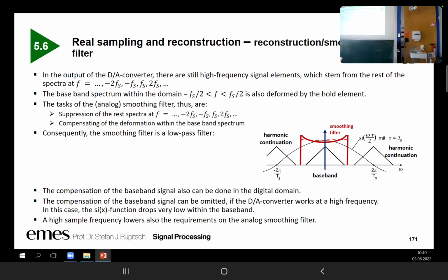Consequently, if we have an input signal with a certain frequency composition, the signal will be damped, but the phase relations of the frequency components remain constant. The signal will be scaled frequency dependent, but the phase relations are not frequency dependent.